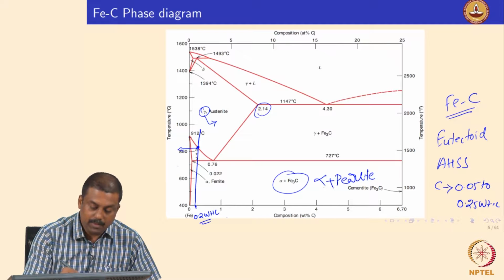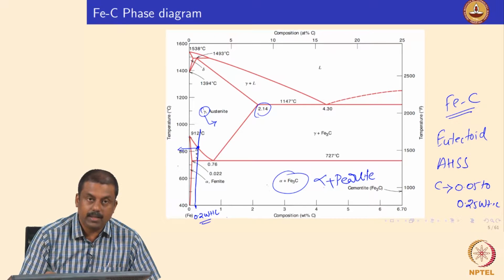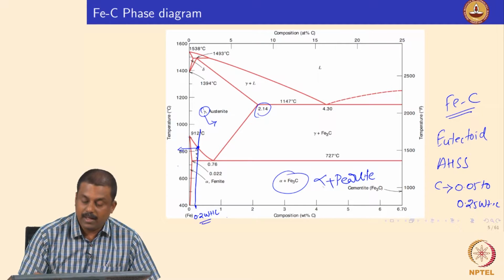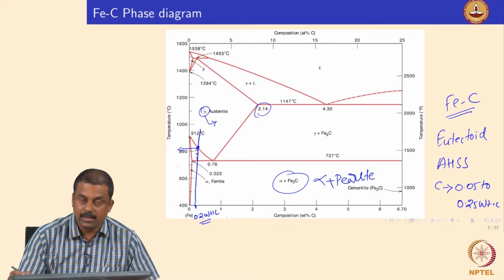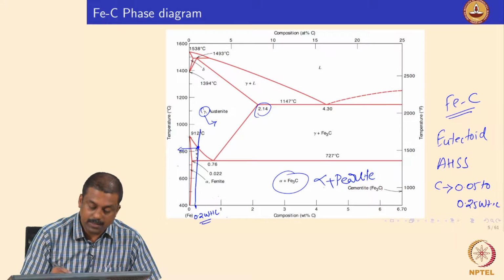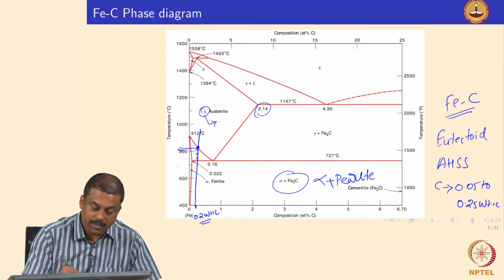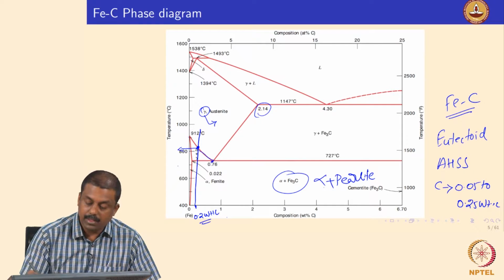When you cool down subsequently to room temperature, based on the cooling rate, you would end up forming a microstructure which can have a mixture of ferrite, pearlite, or other variants of pearlitic structures such as bainite, or even if you cool very rapidly, you may end up forming martensite. So first you need to understand from this graph that, if you have 0.2 weight% carbon and you are cooling down to room temperature, your austenite would keep enriching because of the formation of first the ferrite, and then the moment the untransformed austenite reaches the eutectoid carbon concentration, you will end up forming pearlite.